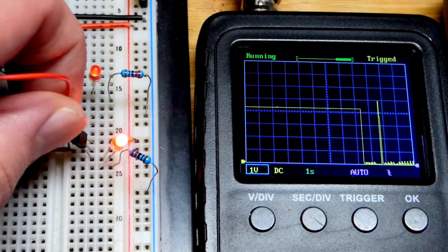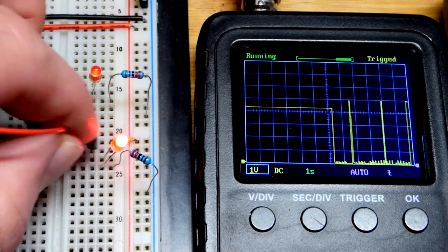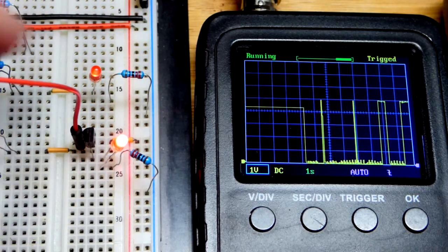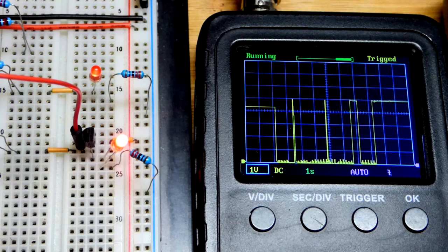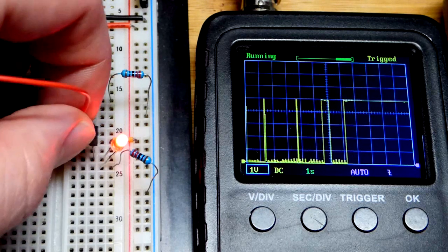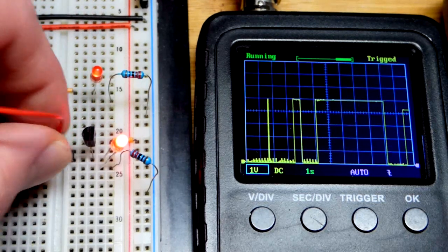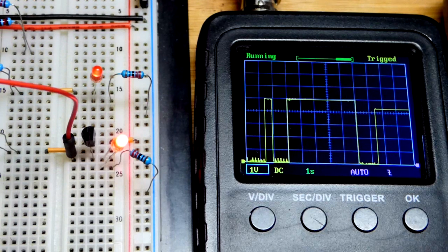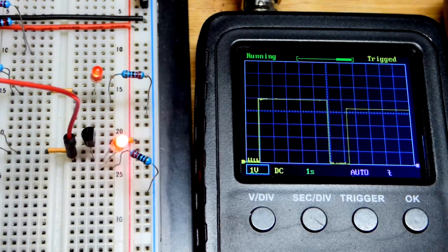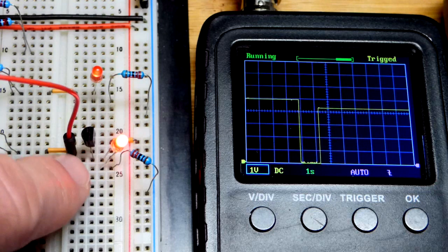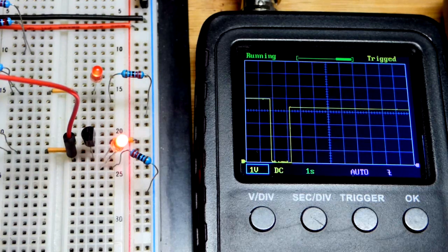Once I get that in the board. There you go. So just a shy bit below 5, not bad though, and then a little bit above 4 right there. So you do lose a little bit of voltage, but that's pretty steady even as the load changes. That voltage will hold pretty steady there. The transistor will hold it.